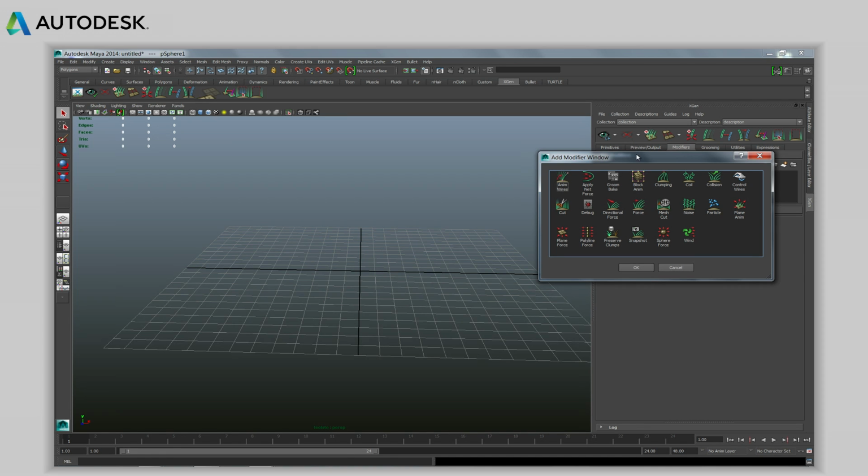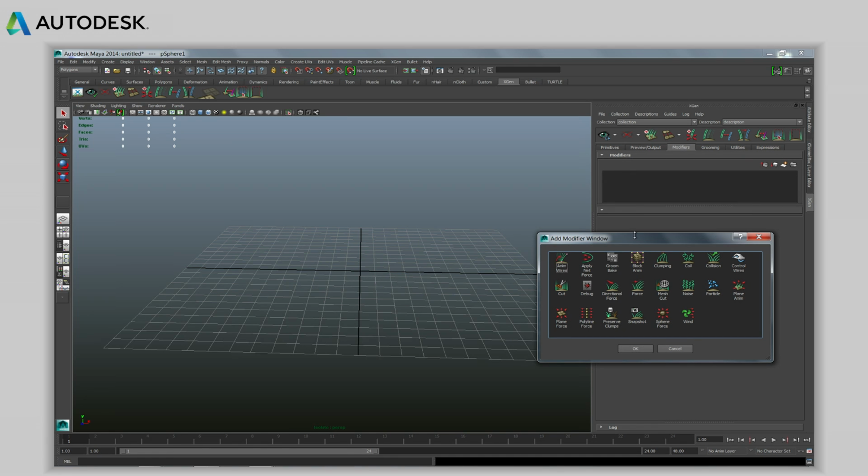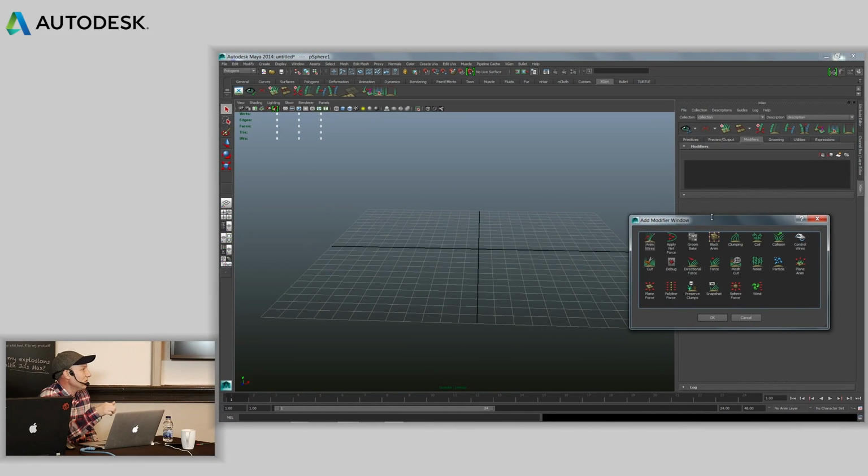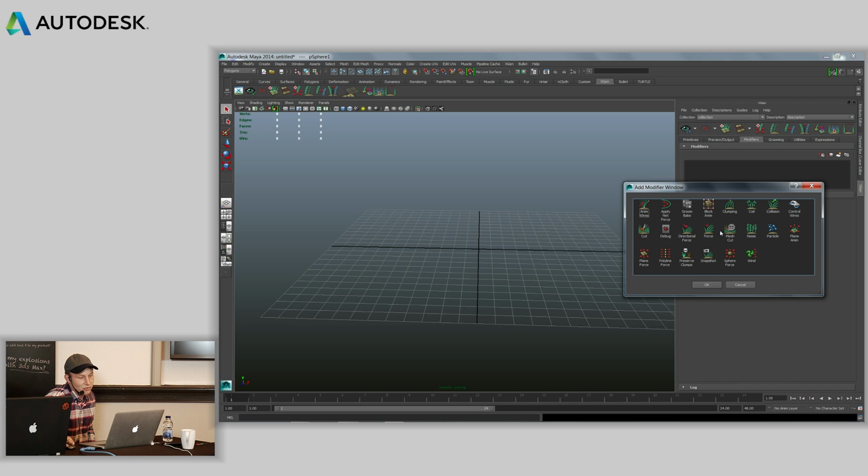The other thing that you can do, if you wanted to do a semi-crowd type effect, I wouldn't say for crowds necessarily, but like you wanted to have wind blow across, where it's going to avoid things and stuff like that. But if you wanted to have a bunch of different random moving objects, the archives, when you create them, are basically making Alembic caches. And those Alembic caches, if you have animation on that, will save out. So if you had an Alembic cache of a tree blown in the wind, you wouldn't have to use these modifiers to make that tree blow in the wind. You could animate the tree, create your Alembic cache, which becomes your archive essentially, and then have that be what gets populated and instanced throughout your scene. And then obviously, you can layer on top of that another set of modified animation that comes through with these modifiers.